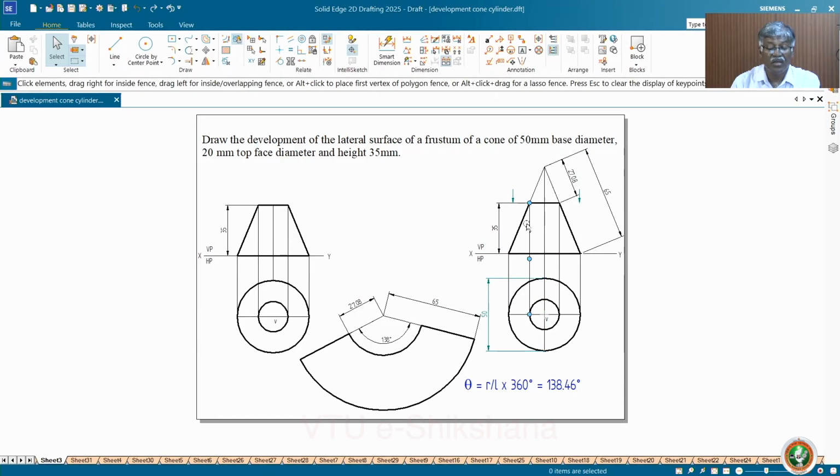Now what you do is, try to draw this figure, two concentric circles, and get the front view. Project the inner circle's end of diameter at a height of 25 or 35, whatever height is given. Then project the axis and project this like this. You will get the apex. Then you measure the true length of the generator. Then try to process by this method, whatever I have done now. So this is about the cone and frustum of cone.